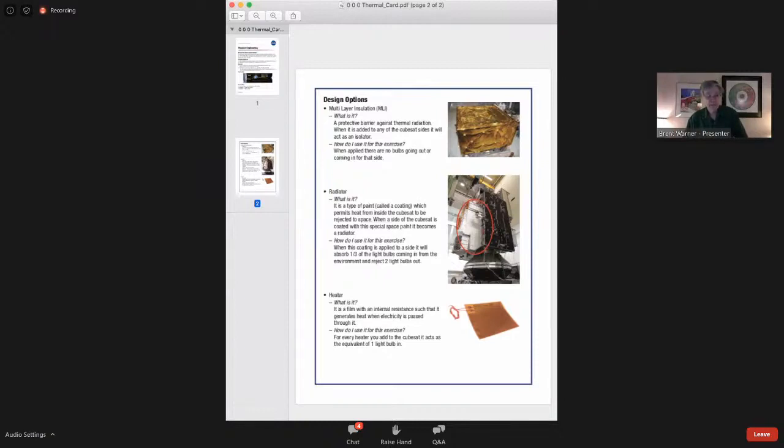Now, the aluminized coatings look shiny metal like aluminum looks, but you don't usually see that on the outside layer. The reason has to do with the way shiny metals radiate. A shiny metal is good at reflecting incoming sunlight, and it heats up, but it's not that good at radiating away in the infrared the heat that builds up.